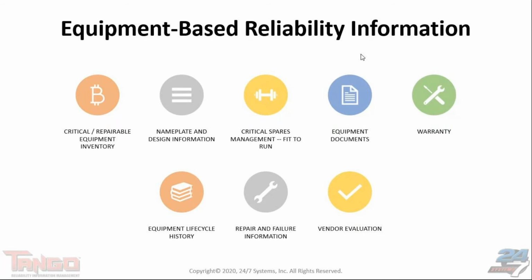Again, the lower line that we're looking at here is talking about the information that you're developing over the service life of that piece of equipment. You're looking at what's happened. Where has that individual motor or pump served over the 8 years that we've had it in the plant? What's the MTBF on that particular individual piece of equipment, and has it varied by the different locations?